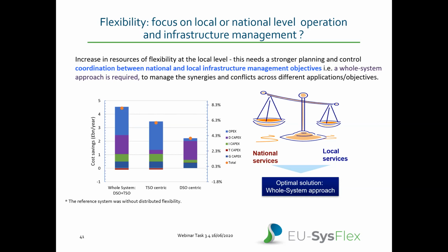Similarly, in the TSO-centric approach, where DERs are used by TSO without considering the need of distribution, the solution will be suboptimal, and it will also require more distribution network to be built. So the challenge is how to maximize the synergies and prevent conflicts between TSO and DSO when they use these distributed energy resources.